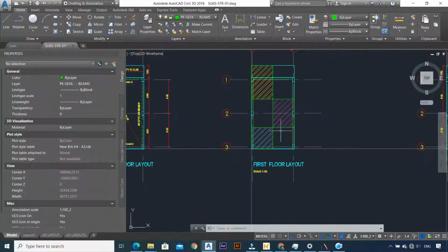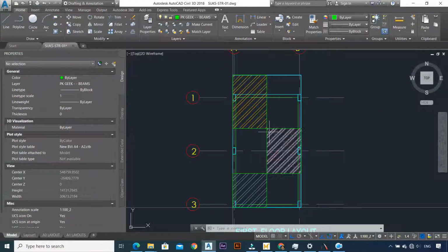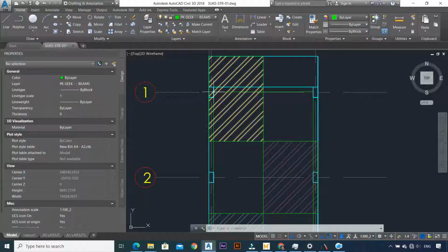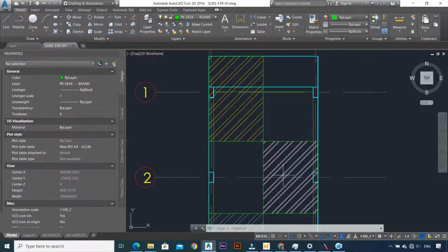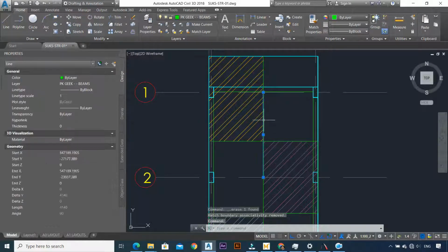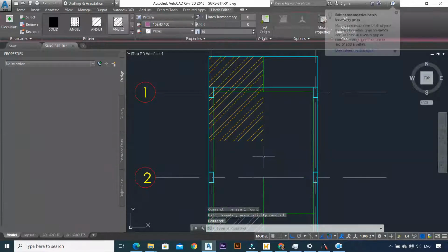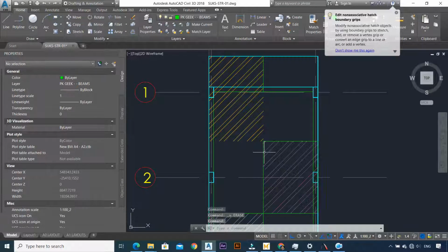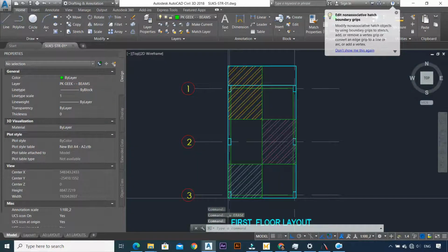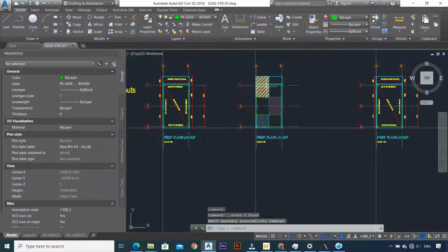What you have done after essentially doing that is you have established your tributary areas. So as I showed you, it's just going to create a line between the two centers of your columns, as we did over there and there. Then after you do that, now we need to remove these lines. We can always remove these lines if you want. Oh no, sorry. Let me not remove the main lines. Let me just remove the squares. If you want, we just remove the squares.